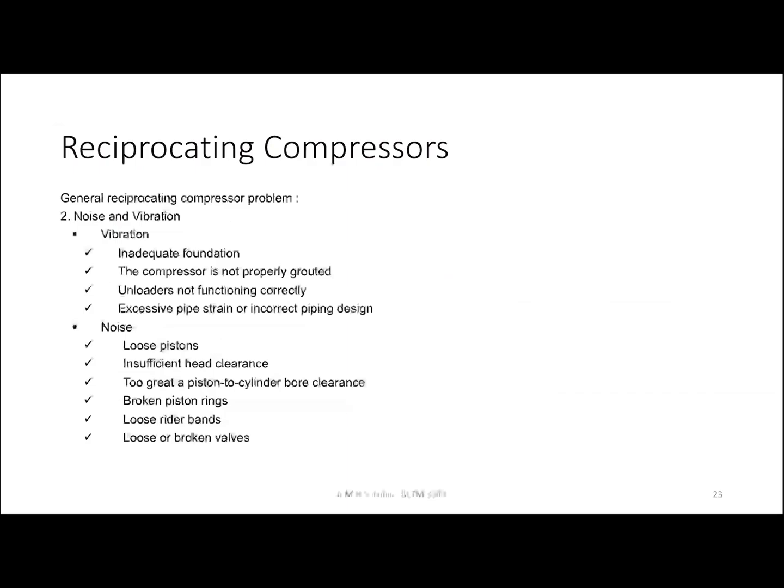Okay. Second, another problem in a piston compressor is noise and vibration. If high vibration happens, it typically can be because of inadequate foundation, meaning improper installation.